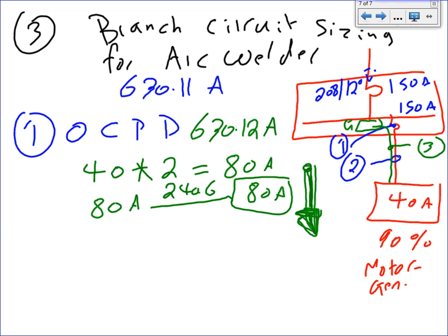Now, I want to bring to your attention, if you read it through, it doesn't say apply the table to it. It says the primary current, or the IMAX. I don't know the IMAX of it, so I'm going to use the primary current, which is that number here. So 200%, 80. Had we ended up with, say, 73, we're going to go down to 70. Am I clear about going down, not going up?